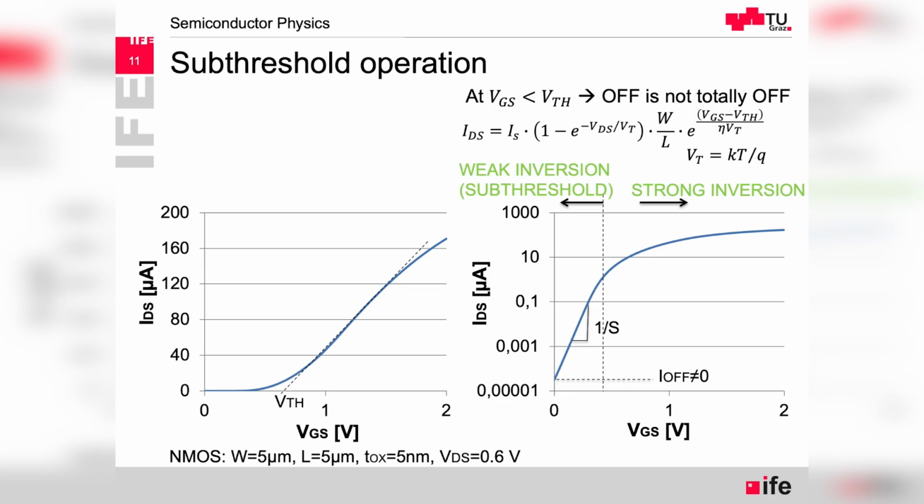Here is a cited example of why low off-state current is important. Imagine that every transistor in a large integrated system had just 10 nanoamps of leakage current between drain and source. If there are 1 million CMOS inverters, then the static power consumption will be 10 milliamperes.